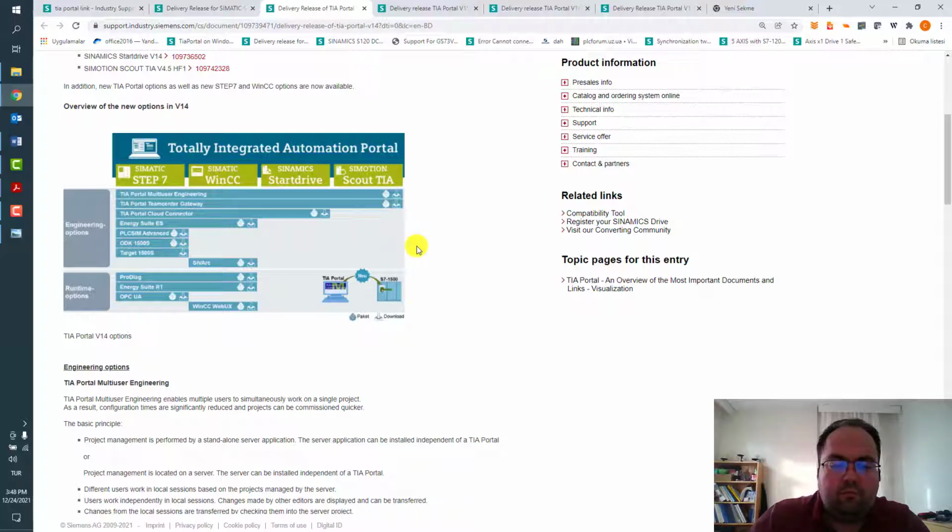What's the difference? Basically the advanced optional package supports multi-instance creation of PLCs inside your computer. You can consider that your computer becomes a software-based CPU. That means you can connect real hardware like electrical terminals via Profinet or Profibus to the CPU, and you can get the real inputs and outputs. Also, communication between CPU and CPU is possible to simulate inside your PC.